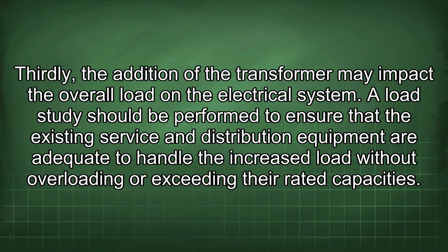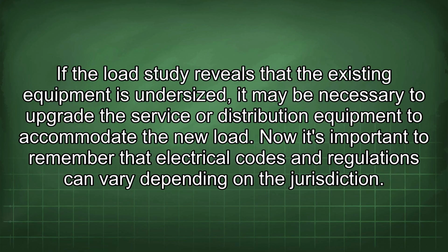Thirdly, the addition of the transformer may impact the overall load on the electrical system. A load study should be performed to ensure that the existing service and distribution equipment are adequate to handle the increased load without overloading or exceeding their rated capacities. If the load study reveals that the existing equipment is undersized, it may be necessary to upgrade the service or distribution equipment to accommodate the new load. Now, it's important to remember that electrical codes and regulations can vary depending on the jurisdiction.